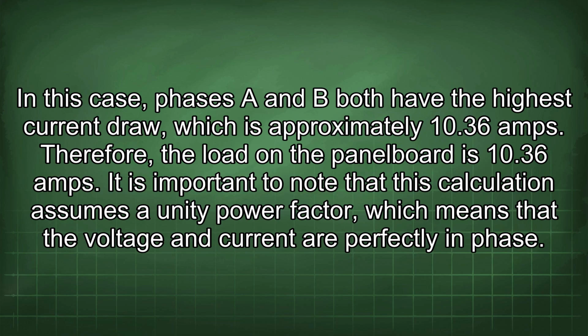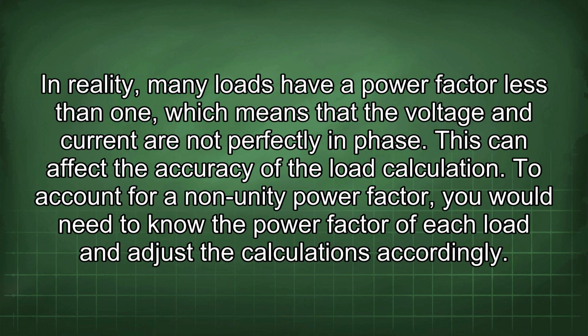It is important to note that this calculation assumes a unity power factor, which means that the voltage and current are perfectly in phase. In reality, many loads have a power factor less than 1, which means that the voltage and current are not perfectly in phase. This can affect the accuracy of the load calculation.